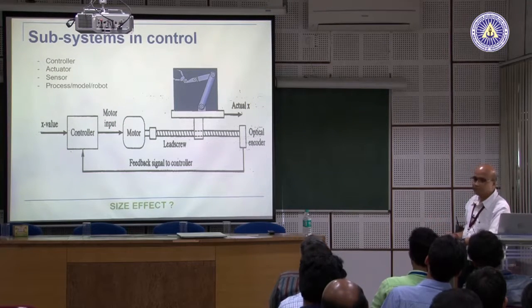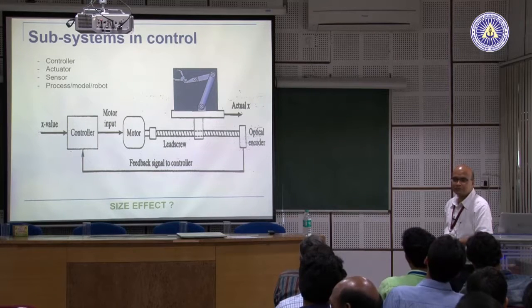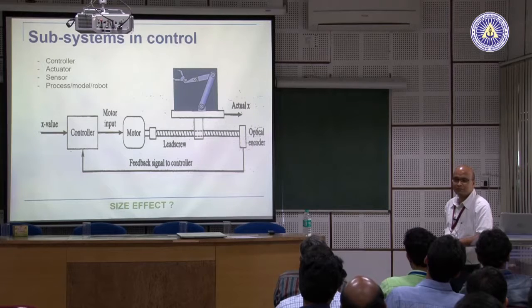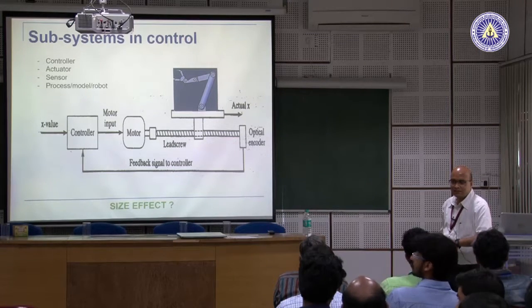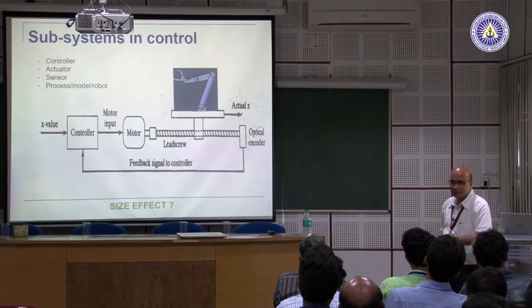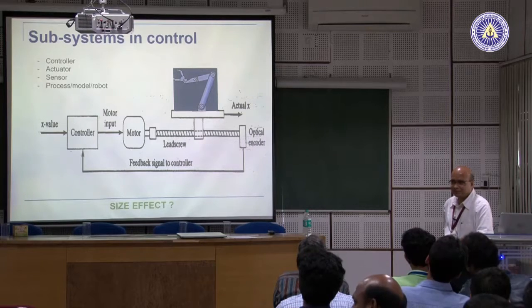Then what is a sensor? This senses any physical parameter which is to be measured. The physical parameter may be the temperature, the pressure, the electricity, the photosensitivity, any kind of physical parameter. The one that is actually doing that is the transducer. A transducer senses and then converts it into an electrical signal. Like the pressure is being sensed by the sensor and it is converted into the electrical form of signal. Then that is a transducer.